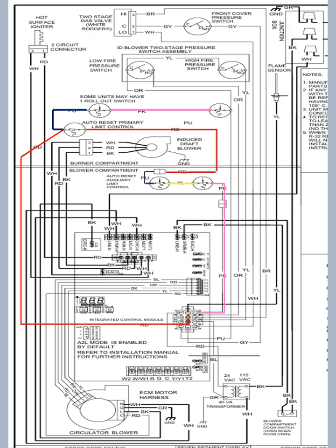Then travels from the outlet of the second rollout switch on a purple wire down to the number 12 pin on your 12-pin connector, proving the rollouts are closed. So now we have all of our switches closed. So now we want to move on to our pressure switches.